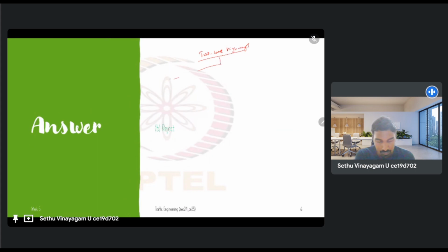right? So here we have the three classes: class 1, class 2, and class 3, right? And the performance measure, as we already discussed, is ATS for class 1 as well as PTSF, right? So the average travel speed and the percentage time spent following. These two measures are used for class 1. For class 2, we need the percentage time spent following only. For class 3, we need the percentage of the free flow speed, right?